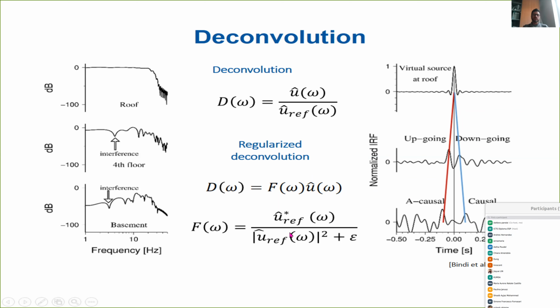What is the advantage in terms of the deconvolution, in my opinion, is that in this way you can remove the source effect, while with the cross correlation, the source effect is still in your signal. So in terms of amplitude, the result of the cross correlation will be proportional to the Green function convolved with the source, while with the deconvolution you should be able to obtain a good estimation of the Green function, even if, of course, band limited, because we have only a certain band, like you can see here, that we can exploit with our spectra.